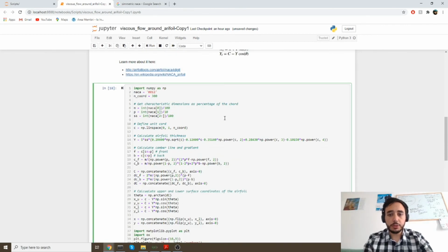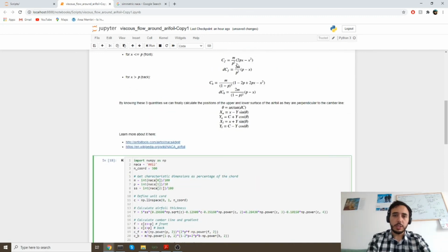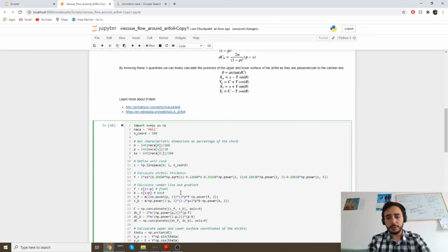So what I would like to show you now is one last thing before we end this video and move on to the next part, where we're going to improve this code a bit more using methods and classes and so on. It's the case where we have the NACA 0012, and the problem with this NACA is that the second digit is 0. If it's 0, it means that we may have a division by 0, which obviously we don't like. We cannot divide by 0. Therefore, we can use a final line of code to add a very, very small number, the smallest possible number that the computer can use, which is not 0.